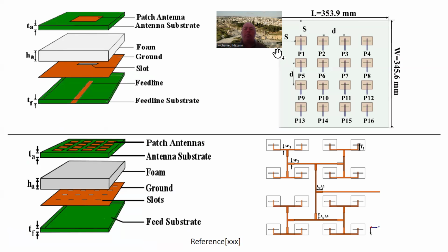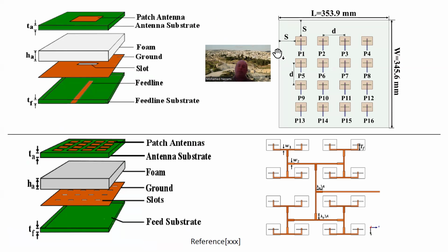Now, the procedure to design a feed network, or even an array of antennas, and I'm not trying to give a lecture on antenna design, but it is related, so we might as well introduce the general concept: you design a single patch or a single unit cell. So you have these layers. Basically, you have the layer that has a feed line, and then the aperture, which we design based on dimensions that will couple the signal through to here. And this is a patch on top. Once this works, you model this. Once you're happy with the radiation pattern, side lobes, gain, and so forth, then you replicate this into an array, for which you have already predetermined what the array aperture should look like, okay? And once you do that, of course, you also replicate the aperture coupling network.